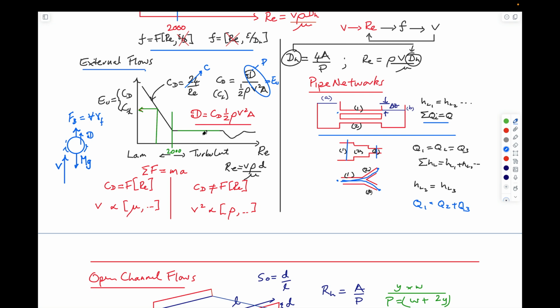And so you need to know that you're on the right regime, so you need to know that you're at the right Reynolds number, again defined in terms of a characteristic dimension, maybe a diameter for a cylinder or a sphere or some characteristic dimension, which you'd typically be given. And from that, the appropriate Reynolds number, you can calculate where you are in Reynolds number space. You can calculate a friction factor.